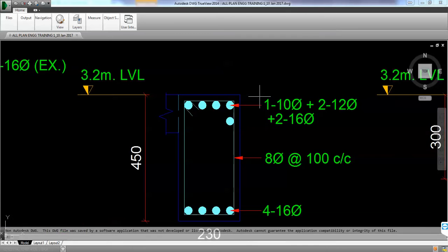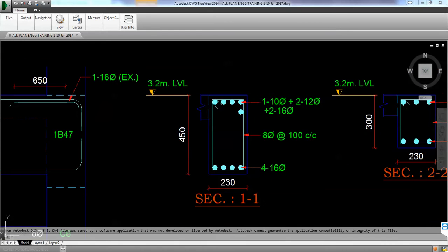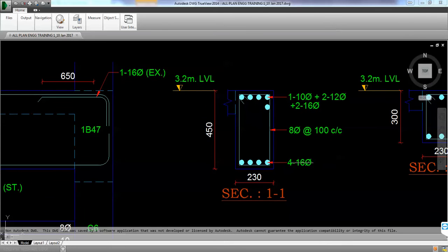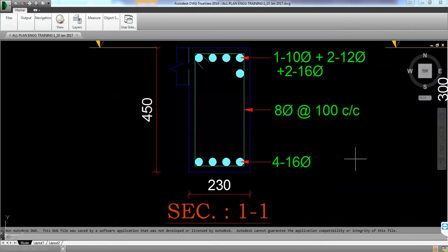However, in the detailing, you have 2 options. You either use Allplan with its automatic features, which give you more precision, meaning we can detail each bar with a circle, or we can use this open detailing where we can manually say which rebars are there.